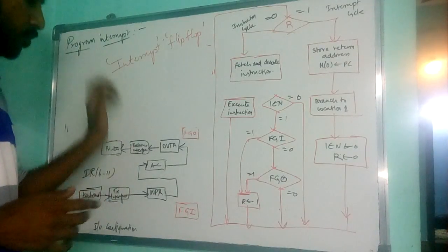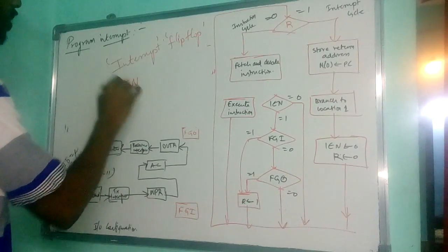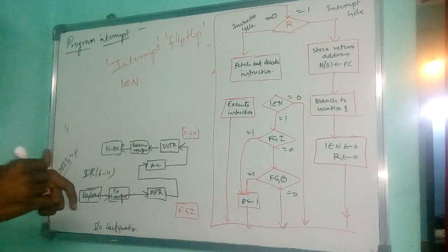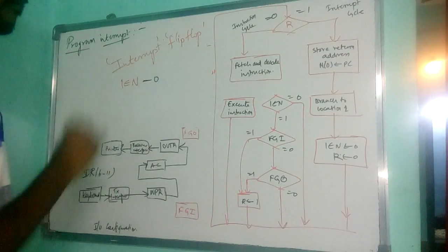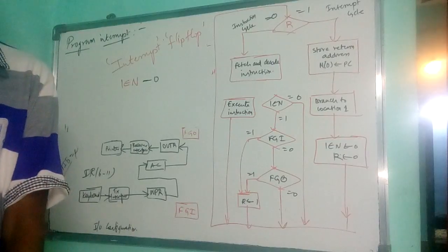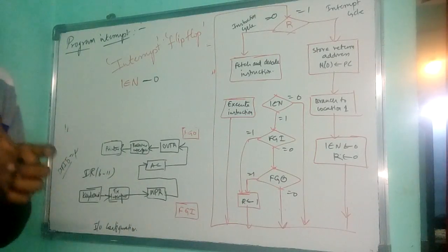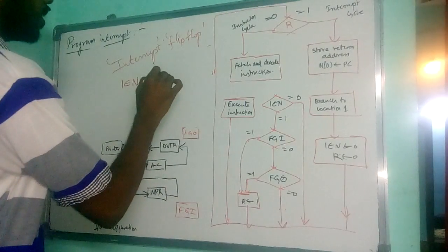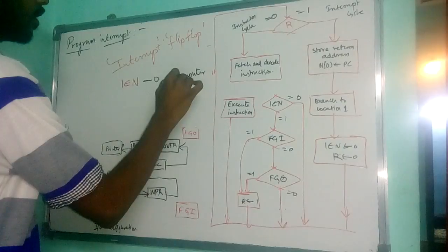So I use my input flip-flop, that means interrupt enable, IEN. Whenever this bit is 0, the computer cannot be interrupted by the flags.